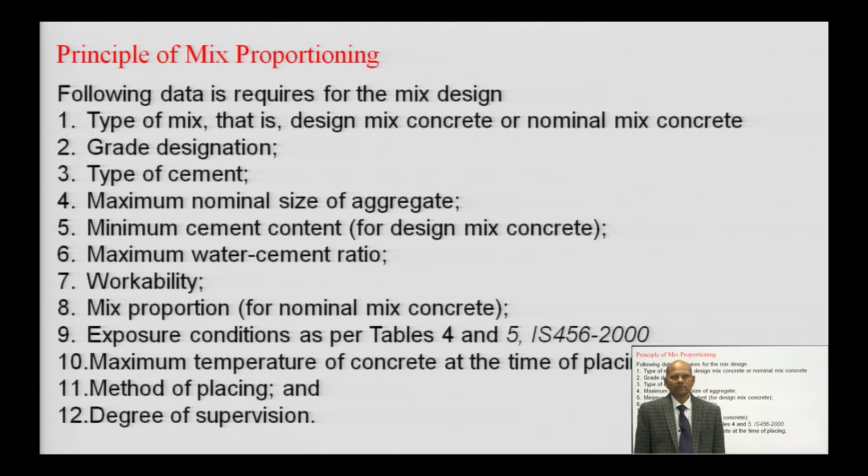Then we have minimum cement content for design mix concrete. In nominal mix concrete, the amount of cement is fixed, that is why it is costly. But if you are going for the design mix, some amount of cement must be restricted, and the maximum content is also restricted. Then there is a restriction of maximum water cement ratio in a design mix or even in nominal mix. So, we can't go beyond that amount.